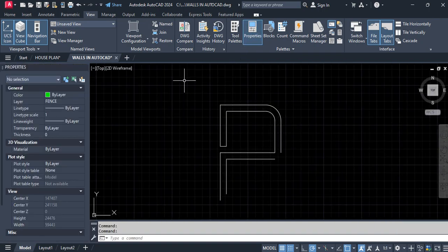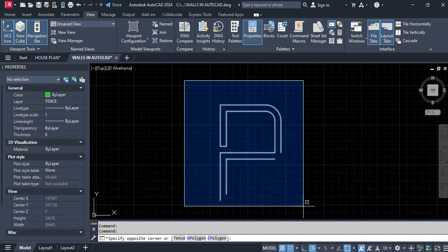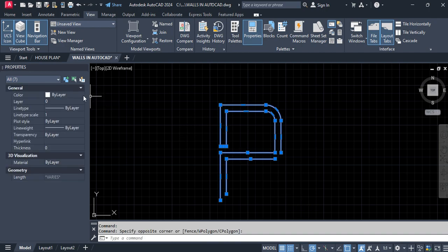So when working with AutoCAD, you should be able to use the view properties to make changes on your selections. For example, if you select this drawing, we could come here and edit its color. We could use these properties quickly to change its layer, and the properties palette or pop-up menu gives us more information about our drawing. So it's essential to use it as you use AutoCAD.